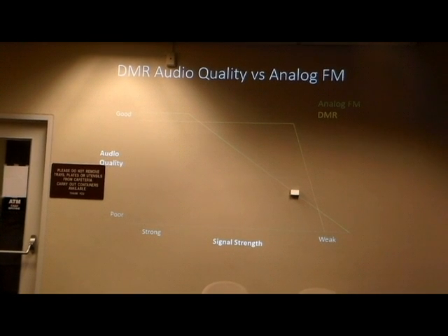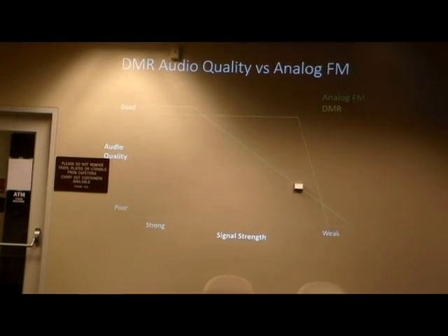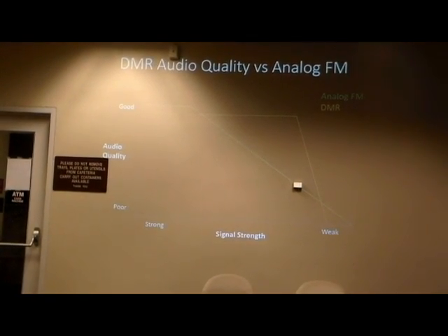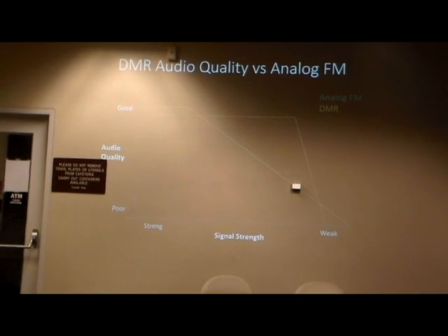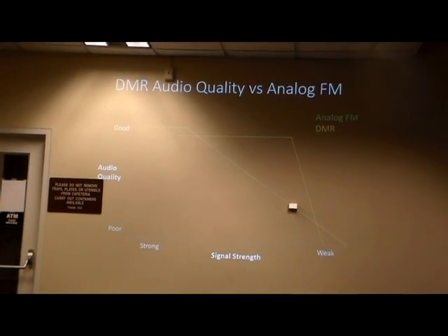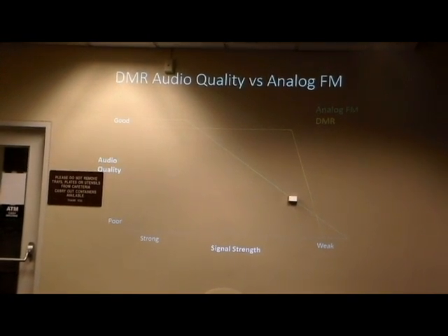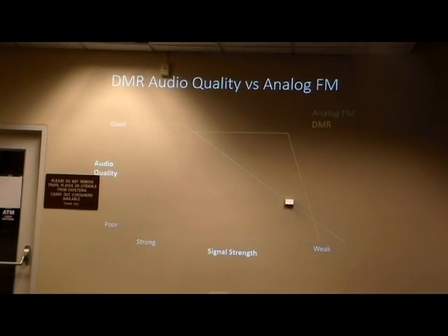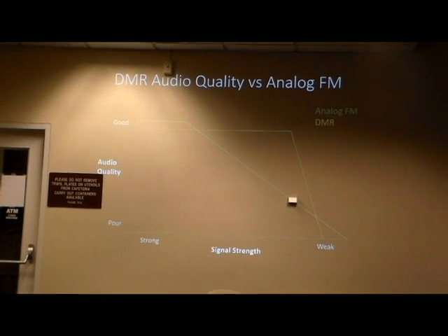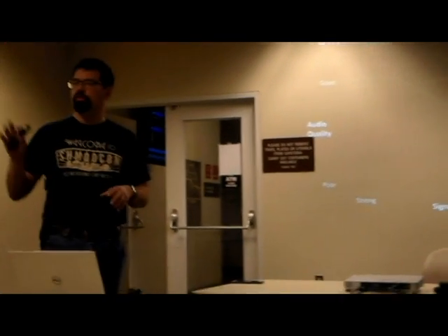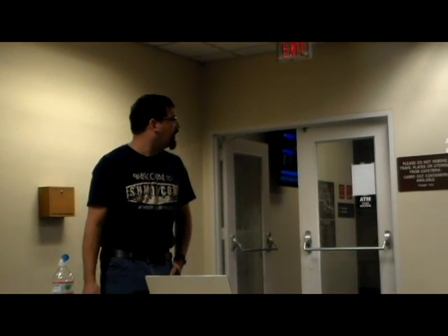One of the really, really big advantages to DMR is that forward error correction, right? Having enough bits in the codec that, if a couple of them get flipped in transit, things that you would normally hear as, say, static on an FM audio signal, it can correct them, and instead of getting a chirp or buzz or nastiness, whatever, you come out with relatively clean audio.